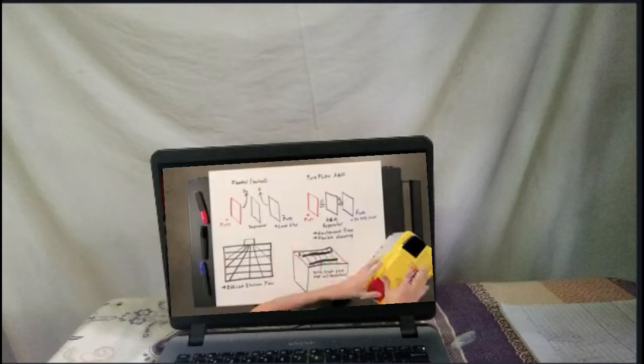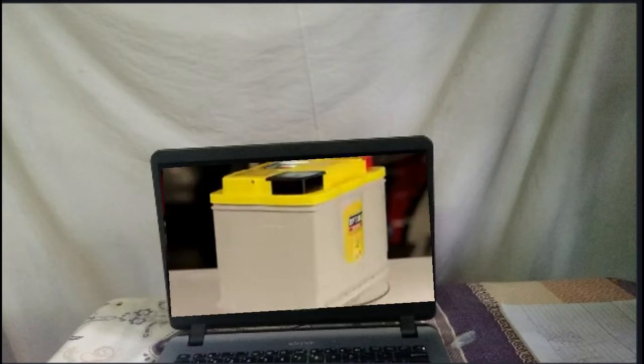Now, this battery was designed for late-model domestic performance vehicles as well as European models. For those vehicles, they require a higher capacity and within a very specific battery footprint. And the most efficient way of doing that is with this flat plate AGM design.